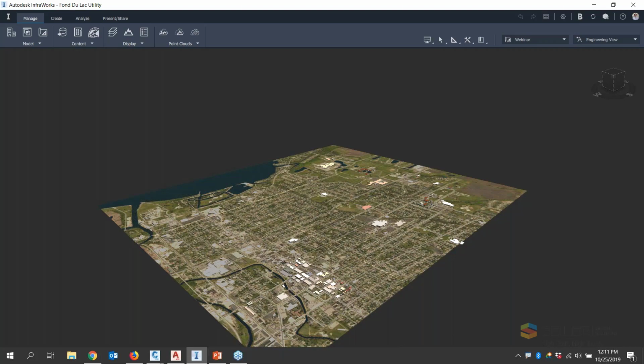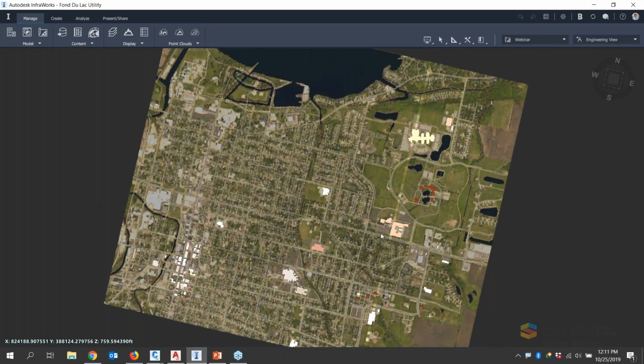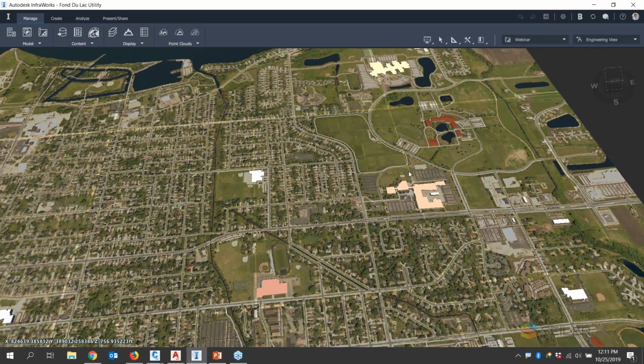Surfaces, roads, if you do design roads in Infraworks, it comes into Civil 3D as a corridor model right off the bat. If you do pipe design, preliminary pipe network, storm layouts, you can do like a road center line, create a road model in Infraworks, add drainage to it, add culverts to it. Those come right into Civil 3D as pipe networks, as corridor models, as surfaces, as proposed surfaces. So you could do your final design, do your preliminary layout, and you're bound by real design rules within Infraworks.